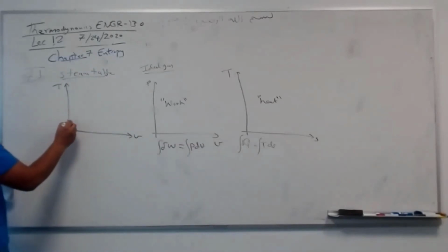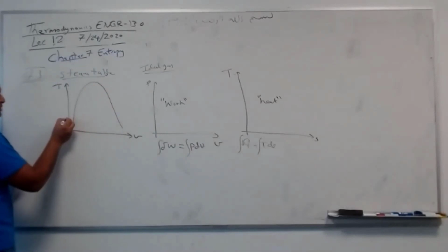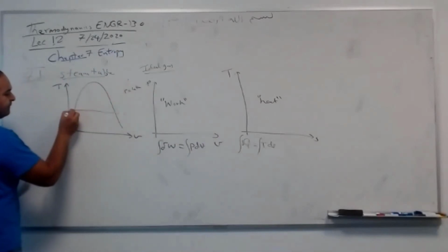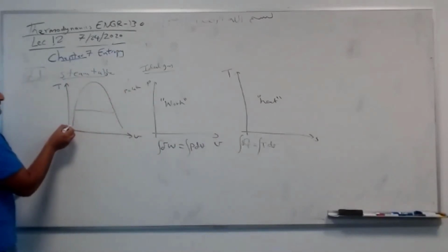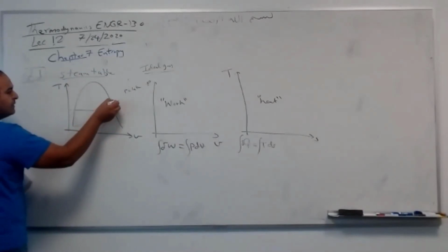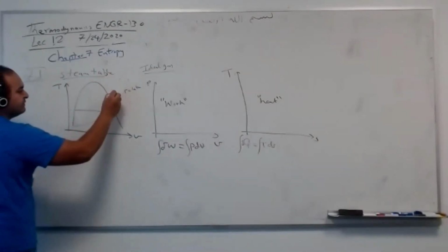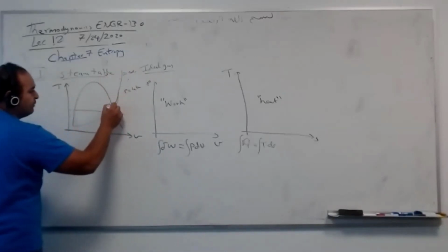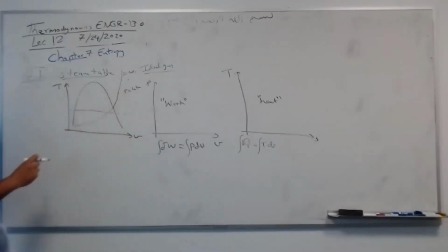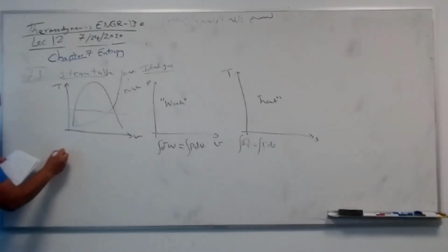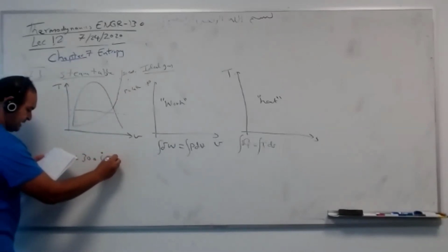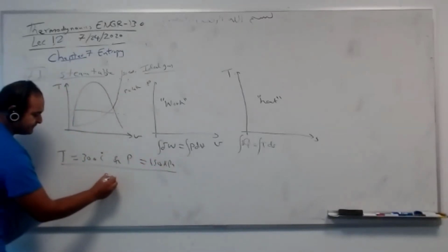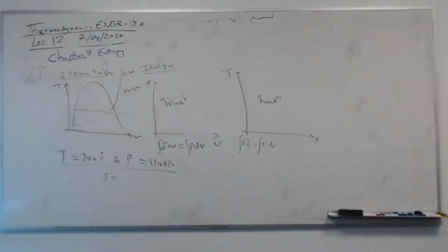So the first one we started with, if you remember, for example, we said if you have a constant pressure line like this, P equal, for example, 1 atmosphere. This is a constant temperature line. We have now a constant entropy line, something like this. S goes vertically, very vertical like this. S equal constant now. And we have charts, Tables A4, A5, A6. Let's take some examples. I give you T equal 300 and P equal 150 kilopascal. Find S. Please, everyone, let me know what S is.